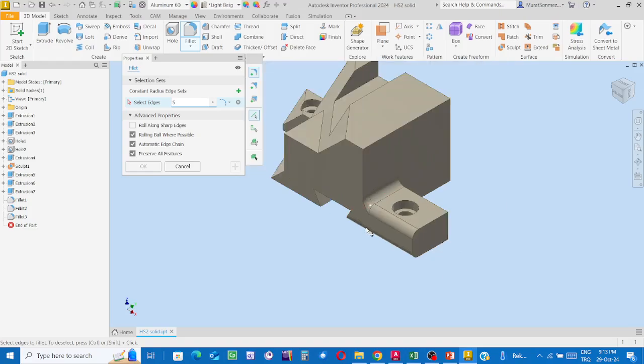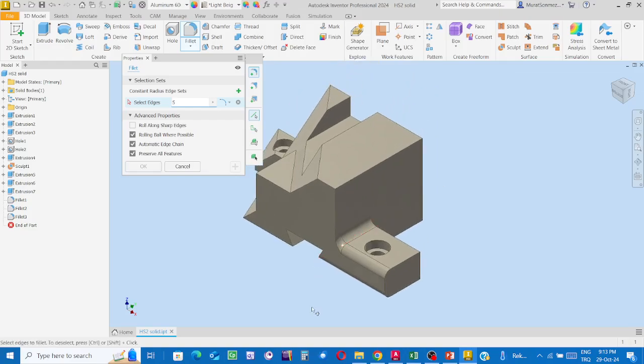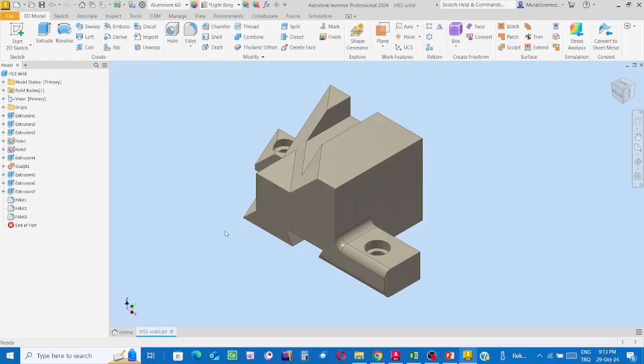This is a fillet. How about chamfer? Chamfer is an alternative process. The chamfering process is applied along an exterior sharp edge. Okay, via cutting the material, we can create an inclined surface along the edge. It is again to decrease the level of risk of hand cutting.